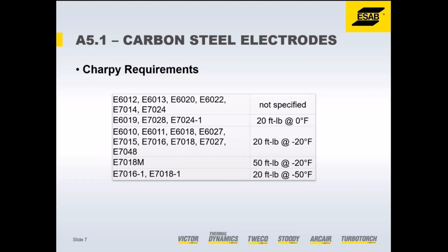An impact test is where a notch is put into the sample block, and that is hit with a swinging hammer, and the amount of force taken to break that in foot-pounds is presented, and the sample is held at different temperatures depending on what's required by the specification.